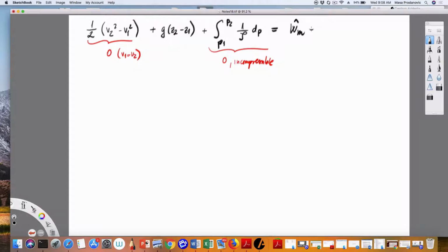And then I have the sum over all of the pipe pieces. So these are my friction losses, and this is how we estimate them for each pipe, which I denote with i. So these are friction losses in pipes, or the straight segments of pipes. And our friction factor is right here. And then minus also friction losses in these elbows.